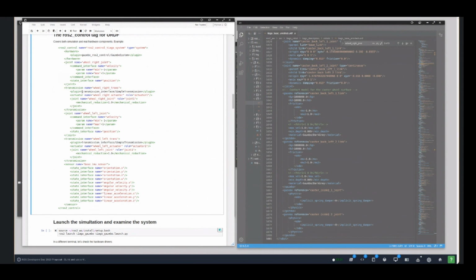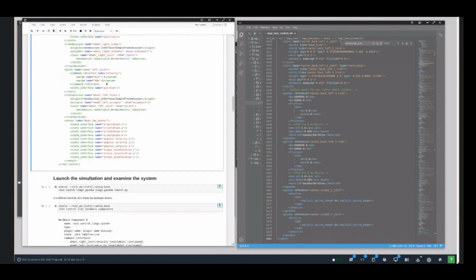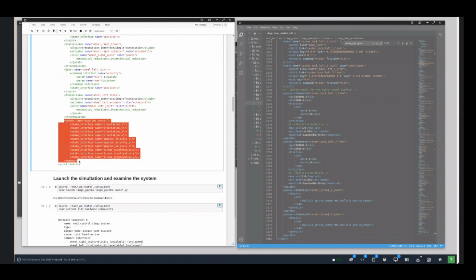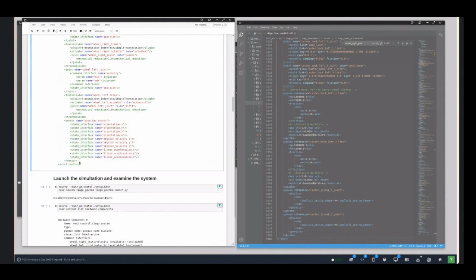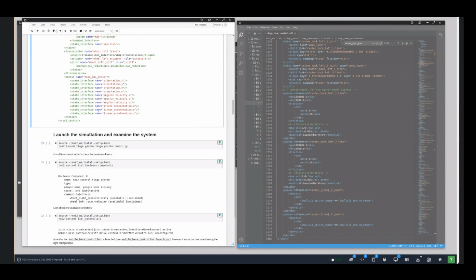For instance, if you have a gearbox or something like that, then it can apply the appropriate reduction rates both to and from the actuator itself. And if you have certain sensors, you can also make sensors available on the ROS 2 control side, so you don't need to publish something to a topic and then wait for it to come back, and then all your real-time reliability or just simply reliability conditions are broken on your robot. So you can hook those up into ROS 2 control directly as well if the controllers need them.